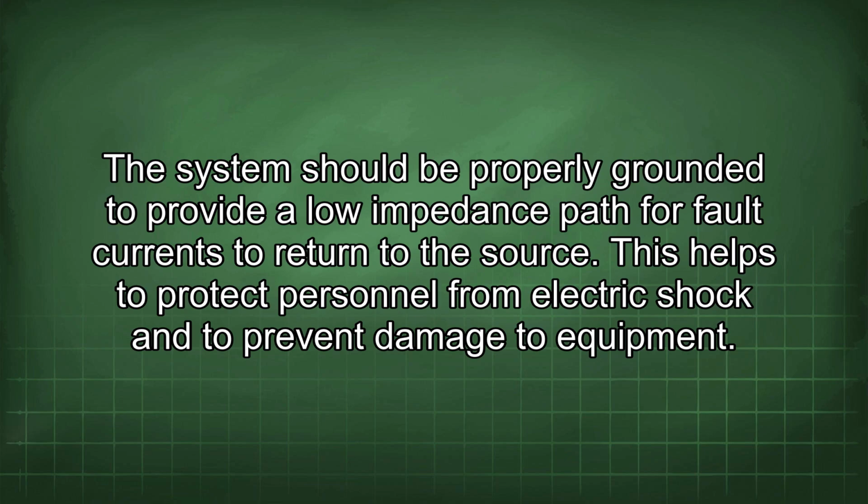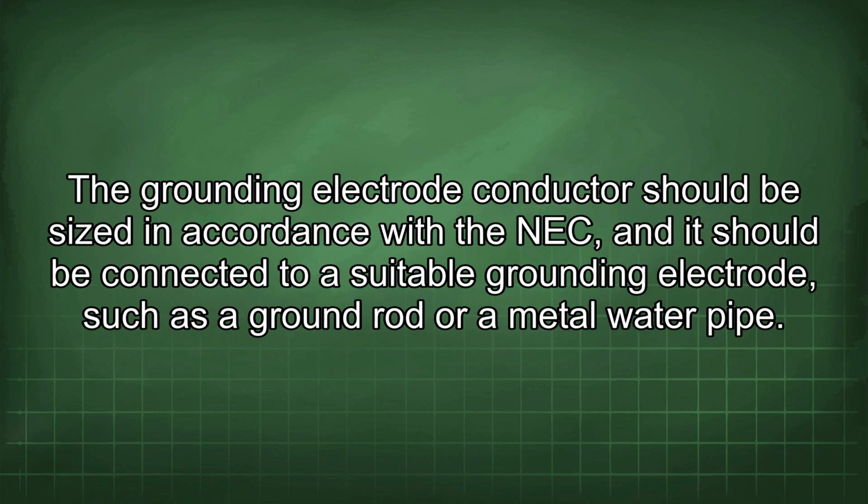This helps to protect personnel from electric shock and to prevent damage to equipment. The grounding electrode conductor should be sized in accordance with the NEC, and it should be connected to a suitable grounding electrode, such as a ground rod or a metal water pipe.